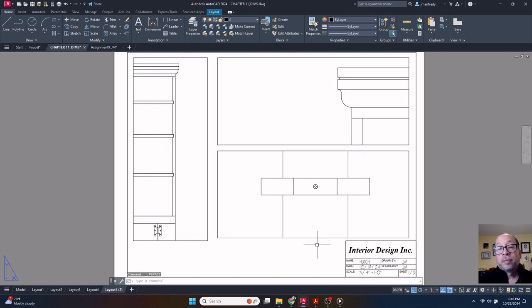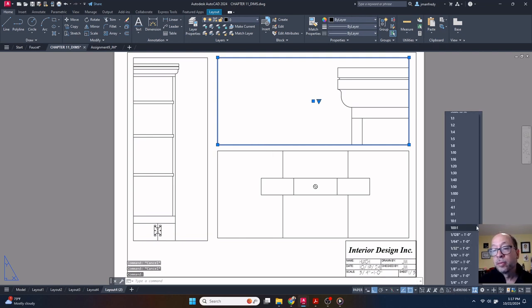And when you do that, each of those drawings has to have the correct scale set up and the viewport's frozen. So this here has been frozen here with the lockbox. It's a padlock that has been locked, so it's 1.5 inches equals a foot. We're good there. This one here is going to be 6 inches equals a foot.